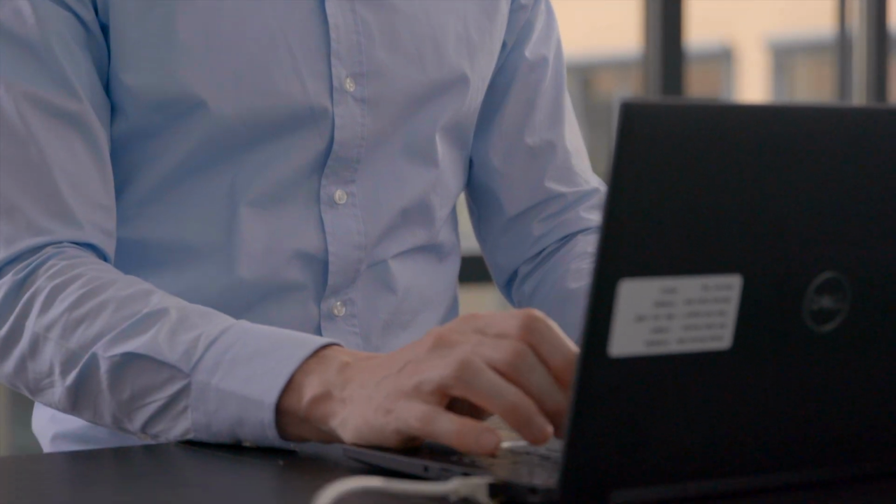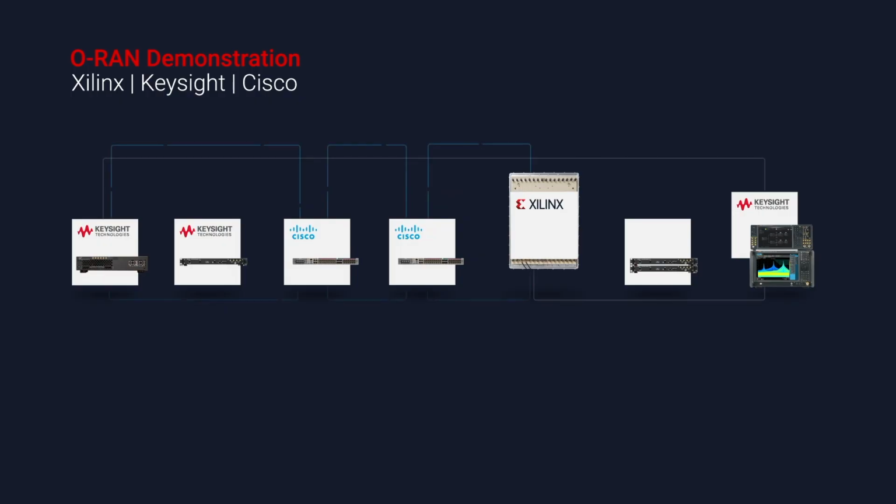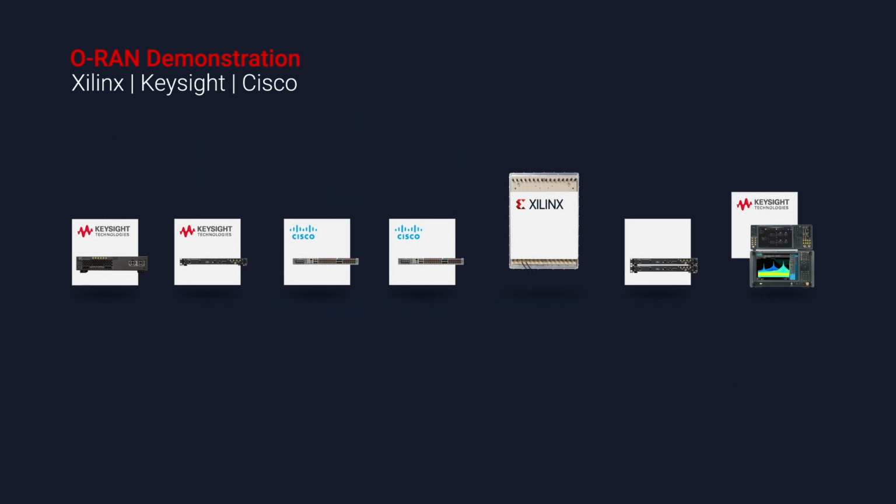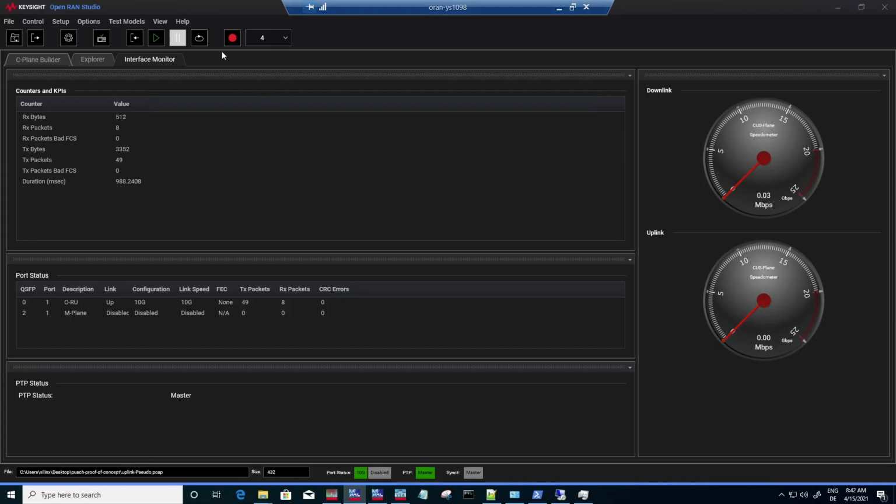Now we're ready to execute the test. The Keysight Open RAN Studio player sends C-plane packets through the FH network to the Xilinx RU. At the same time, it triggers the signal source to send the uplink RF signal. The RU receives the signal and sends back U-plane packets to the DU emulator. As you can see in the traffic monitor, there's only very little C-plane traffic going from DU to RU, and considerably more U-plane traffic from RU to DU.